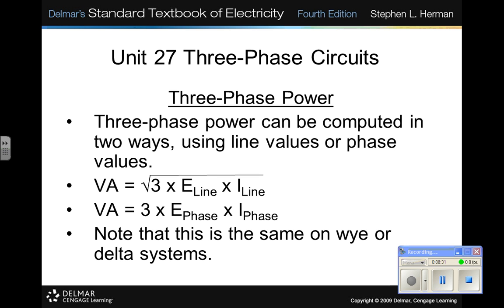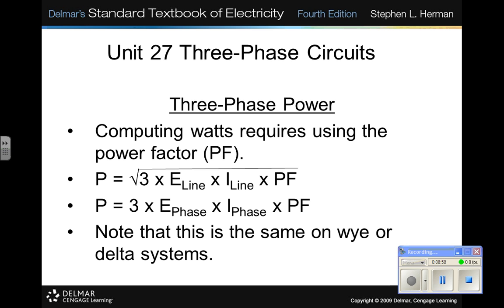And besides, one of the rules we're going to start using is when we're doing three-phase circuits, stay in phase whenever possible. Look at phase, because we'll do a drawing later and what you're looking at is what's happening from one winding to the next winding. And that's a relationship you need to look at. Line values don't always reflect that information properly or easily understood.